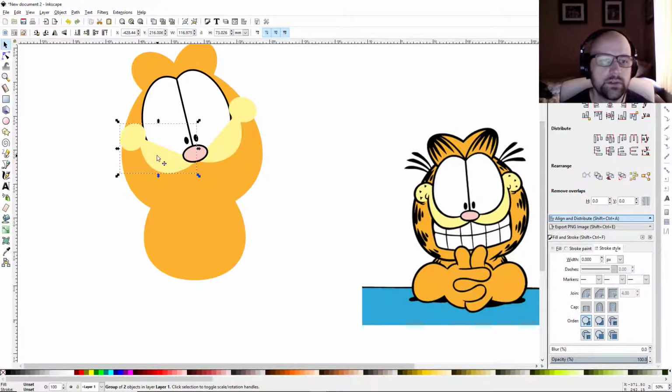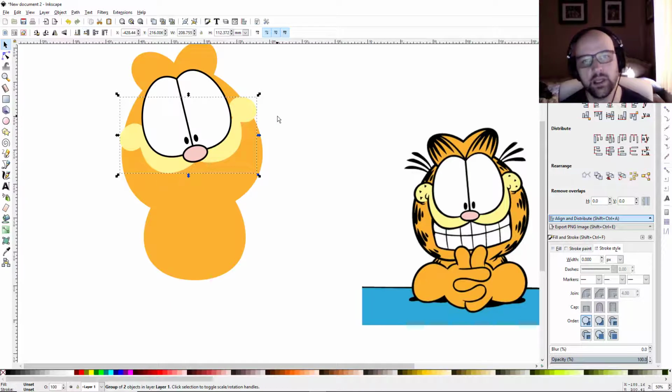Now let's click that, hold shift, click on the other one, hold control and hit G on the keyboard to group those together. Now we want to come up here and move these down 1 step until they're underneath the eyes. And that's all it took, just one step.